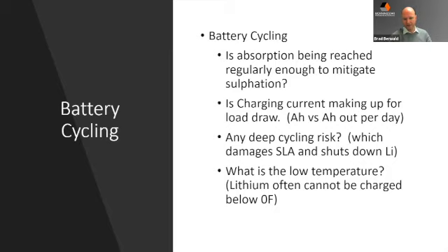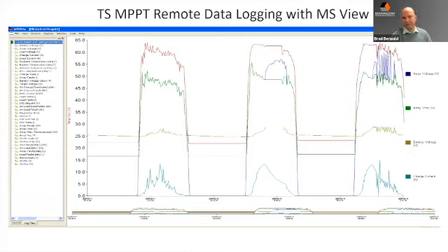And lastly, low temperature has an impact on all systems. PV modules happen to like it. Batteries definitely do not. In the case of lithium, as it's being used more and more, sometimes there's an evaluation of a site. Northern Canada may not be a candidate for lithium, but Florida most likely would be, because of the temperatures. They typically can't be charged below a freezing point. But as we're seeing more and more, the technology is always changing, and with some of them having heaters, maybe that is an opening for more lithium penetration in those remote applications.